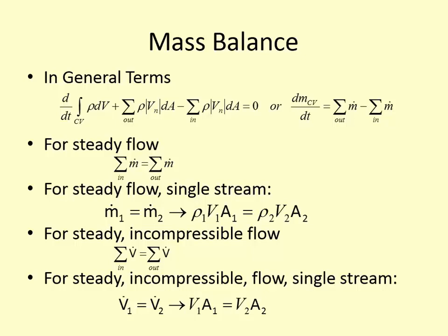If it's steady incompressible flow, meaning that the density is not changing, we can also say that the volumetric flow rates in and out are equal. And then again, if it's steady incompressible flow, single stream, we can make that further simplification where we just have V1 and V2.